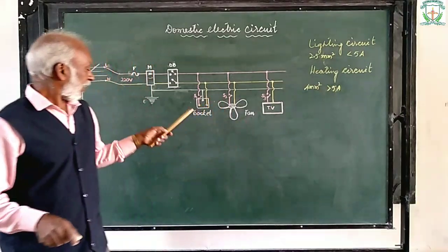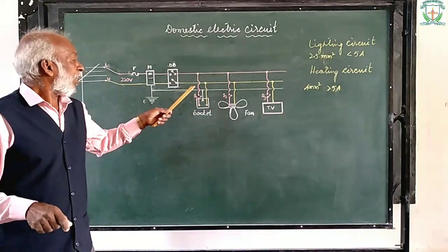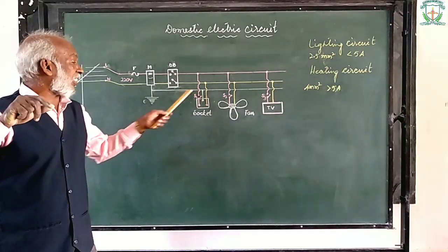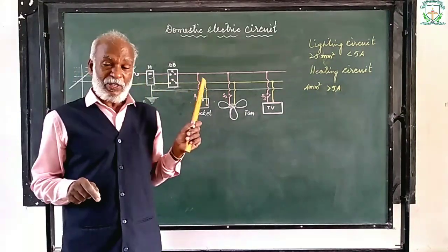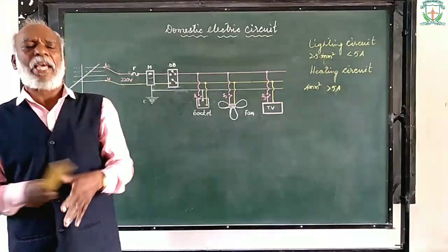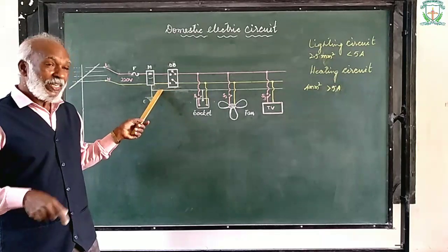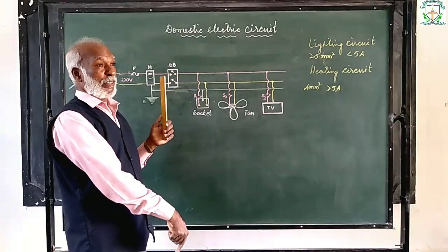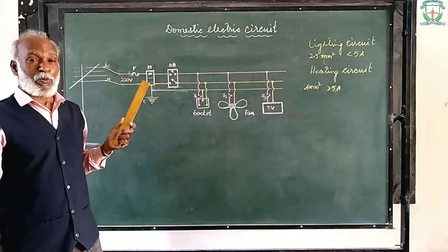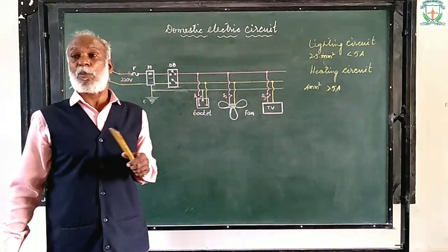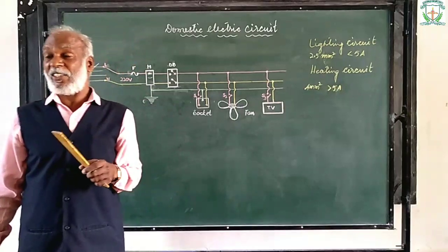So, the machine is faulty and there is some leakage. In order to pass the leakage current easily to the ground, you need to provide a low resistance path for it.